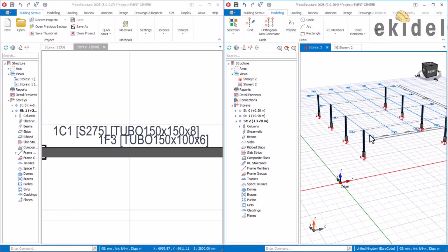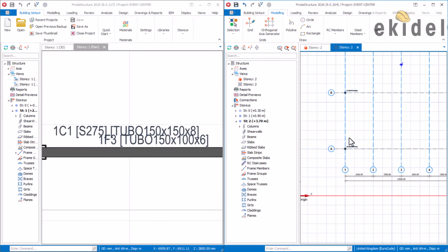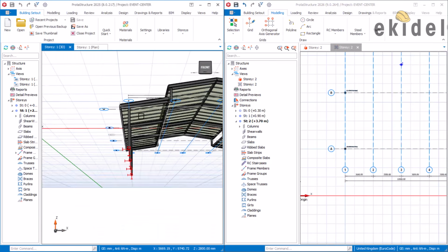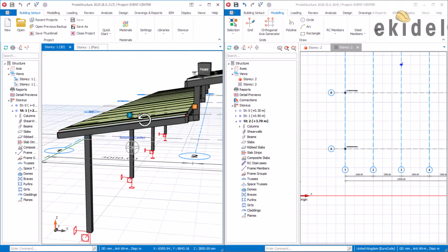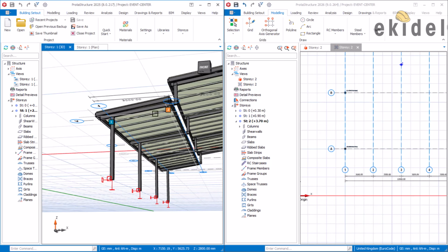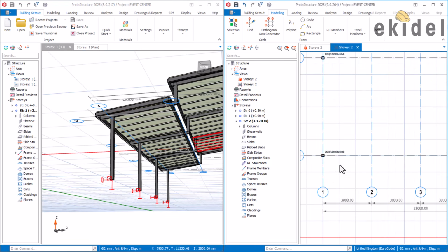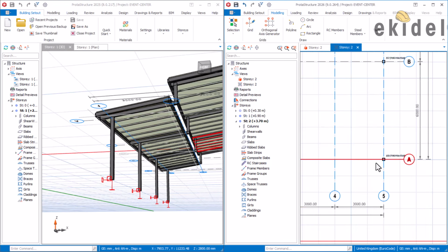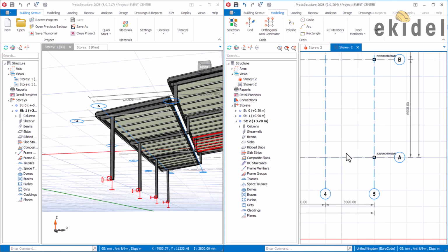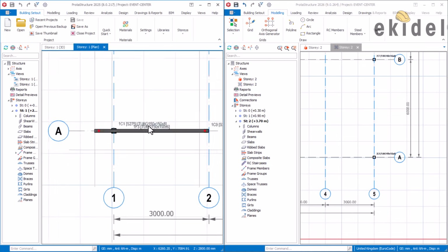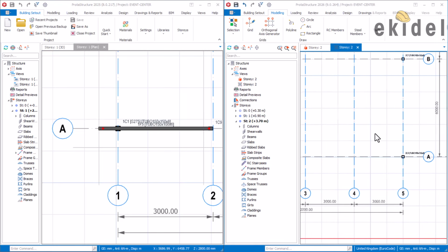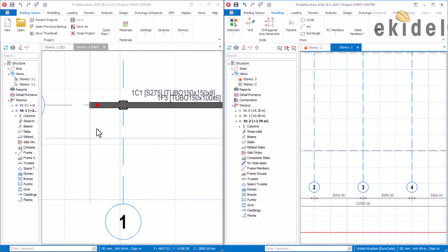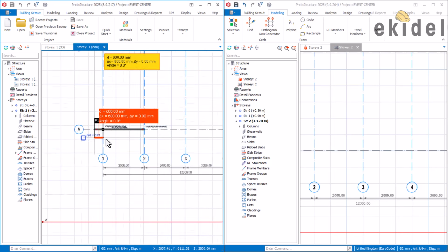So next we insert our beams. To do our beams now, which is this beam that you are seeing here, this inclined first beam, that beam runs from this point to this point, and from grid line 5 to grid line 4. So we are going to insert that beam, and then we are going to insert an eave section. There's an eave here, and this eave is 600. Let me see. Yeah, 600 left and right.